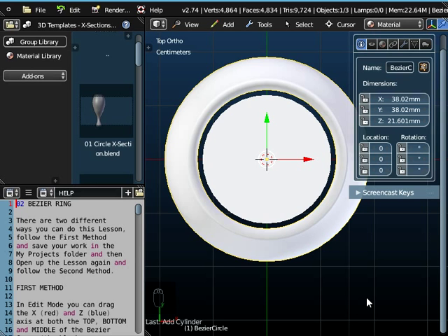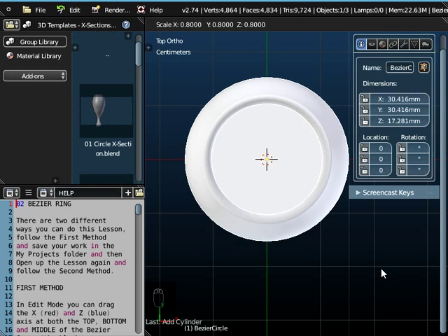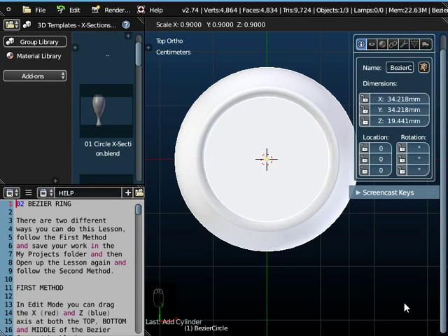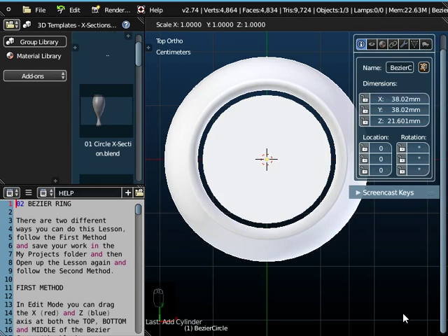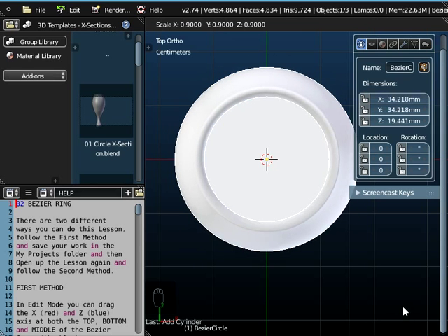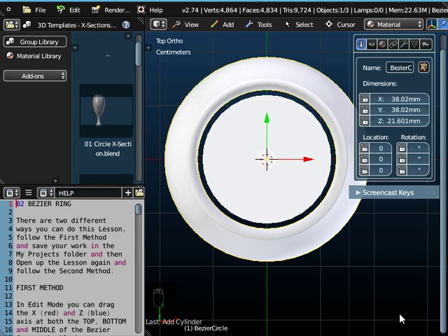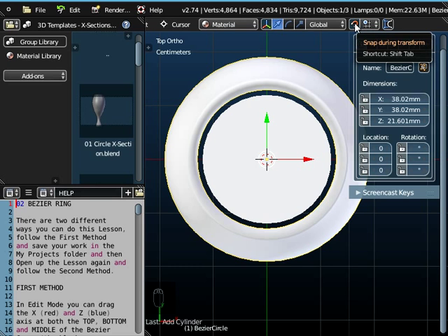I can scale down the size of this ring. And we can scale in FluidDesigner by pressing S on the keyboard. Now before I do that, I'm going to move the mouse right out here to the bottom right hand corner, because the position of the mouse does affect how things scale. So if I do S for scale, and as I move the mouse in, you'll see that it changes scale. Now at the moment it's jumping in increments according to the grid. So I need to cancel that with the escape key. And what I want to do is I want to switch off my snap.